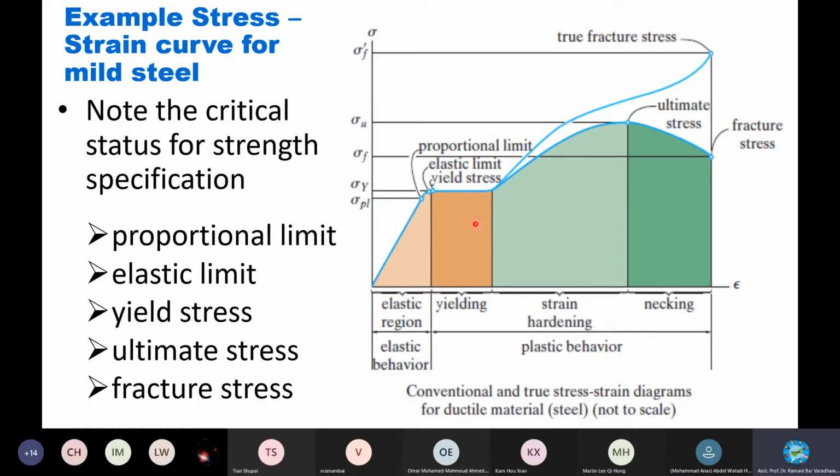But in the plastic region there is also a variation due to the tensile strength of the member. It has some yielding, some strain hardening, and then only necking starts. All these responses are in the longitudinal direction. And in the other direction, which is the cross section, there is also a response to yielding, in response to the load applied. That's why it is important that you know the tensile strength, the ultimate strength of the member that you have chosen for your design, and the property of the material governs. So every material is tested before use for construction or for manufacturing, assembling, right?